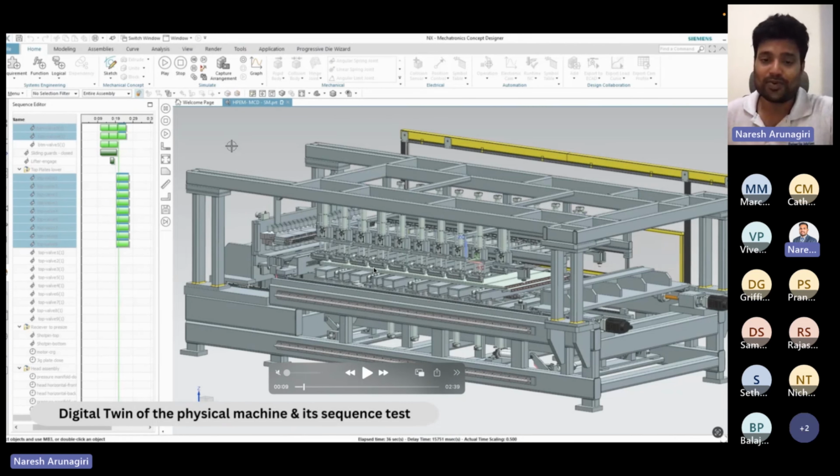So when we start doing that, we want to check if the cylinder is performing as it's programmed. You can see here, we started giving manual checks. We turned the cylinder on and off and saw if it is working or not. Once it's done, yep, the cylinders are checked. Let's move to the servos now.